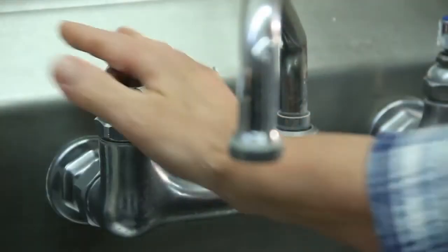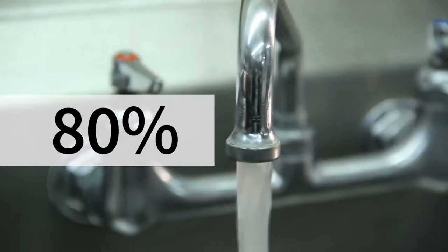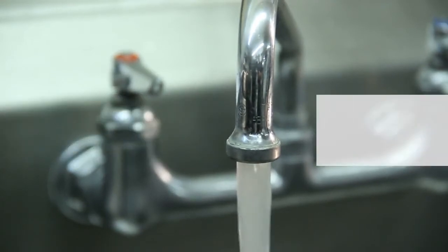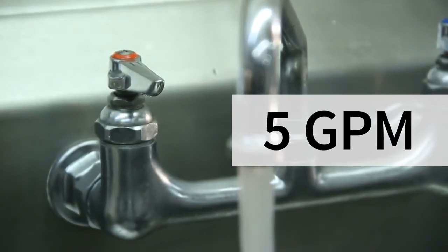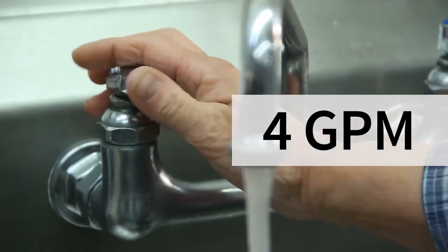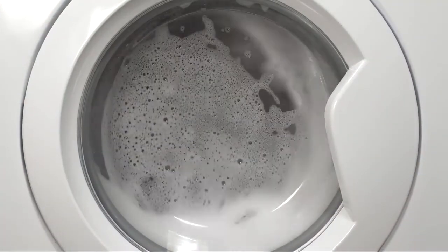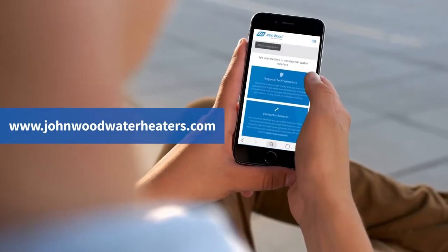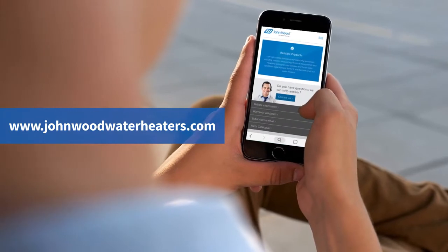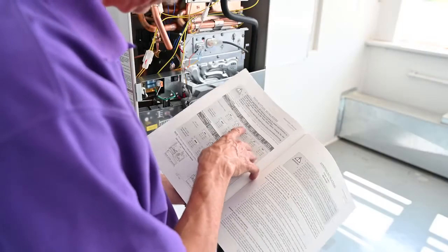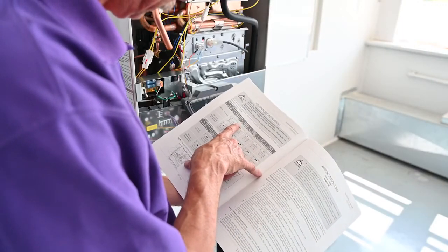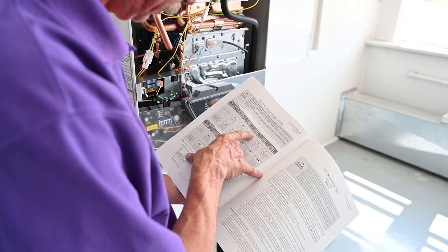A general rule of thumb is that 80% of the total flow rate is going to be hot water. So, of the 5 gallons per minute demand, 4 gallons need to be hot water. Now that you have your temperature rise and required flow rate, you should review our online product literature or spec sheets to confirm which tankless model will effectively meet the hot water demand for the household.